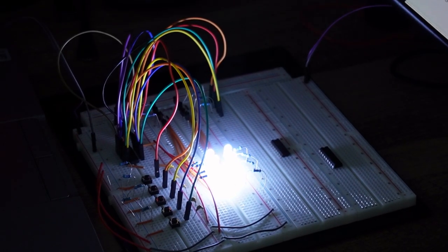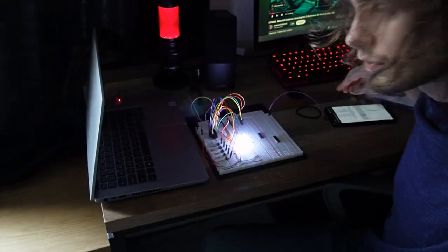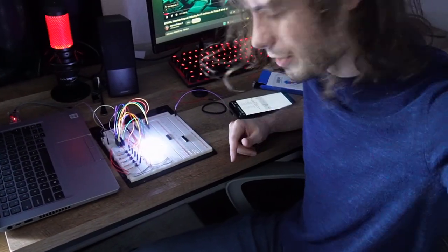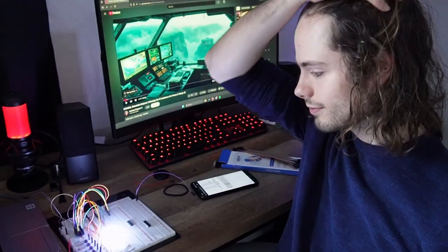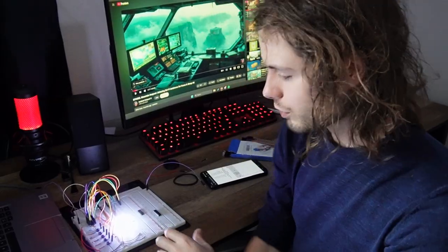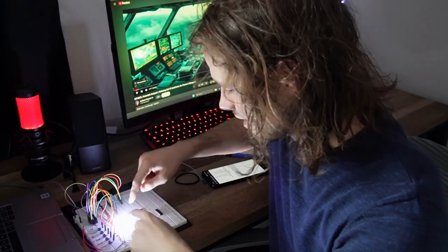And now, for the circuit, I have to say I did not include the Darlington. It's actually right here. It's doing nothing, just because it's a bit easier to just wire these all to ground. So with that in mind, you'll see that the grid is side by side. It's hard to get a perfect 8x8 on a breadboard.